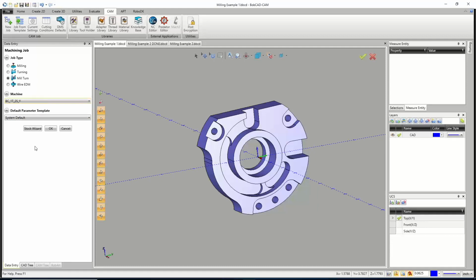If you don't have a Y-axis, that's something we'd have to look at and see how we machine some of this stuff, because you might not have the reach, or we might have to make sure that the table, which we call the table but it's really the spindle, does more rotating than some of the other stuff.